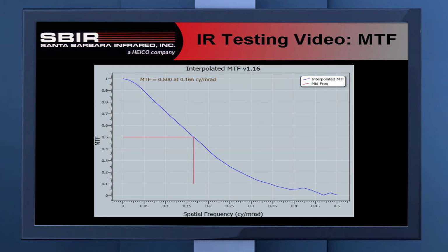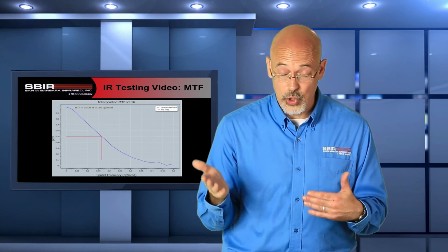And when that maps back into our lower frequency stuff that we're interested in, it is occurring down in the places where the result is around 1 anyway. That doesn't have a big impact on our final result. So by interpolating the slanted edge, we get an effectively higher rate that we're measuring, and we get a much nicer curve. And this next curve is actually coming from an interpolated result.